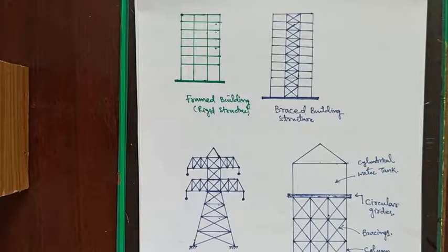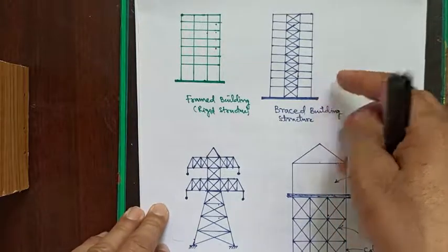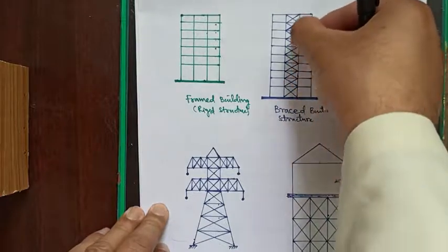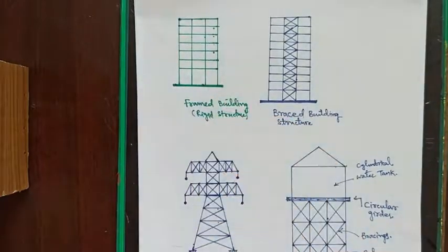Bracings are mainly provided to resist lateral loads due to wind and due to earthquakes and to provide stability to the structure. In braced construction, beams and columns are designed for vertical loads only, assuming the bracing system carries all the lateral loads. Whereas in rigid frame construction, the frame structure is designed so that the connections between the structural members are moment resisting. That is, they are capable of transferring the moment in addition to the shear forces. In summary, in braced frames, columns are designed to resist mainly compressive forces, whereas columns in rigid frames are designed to resist bending in addition to compression.